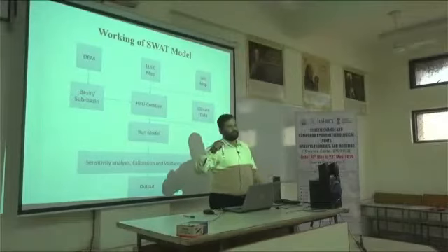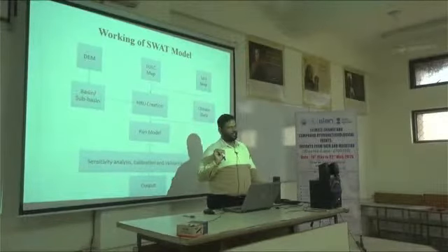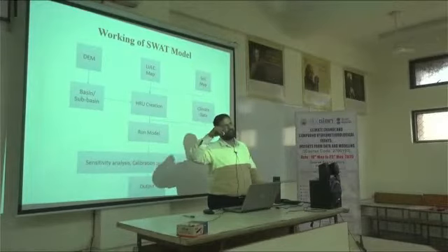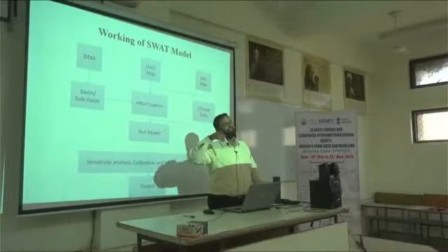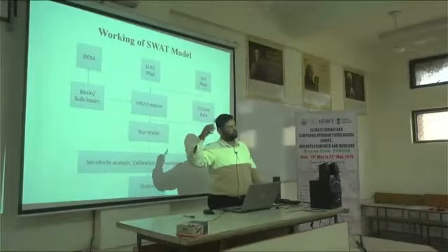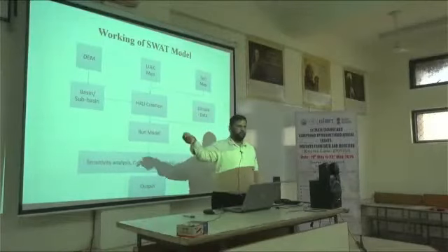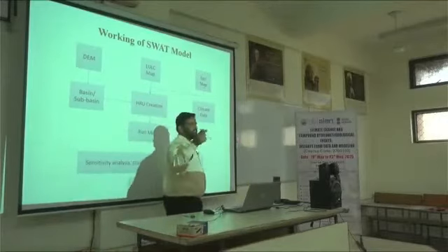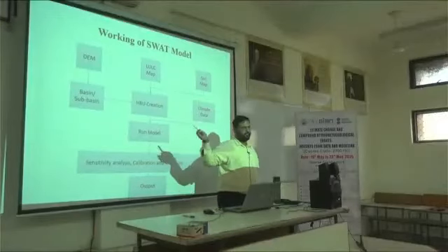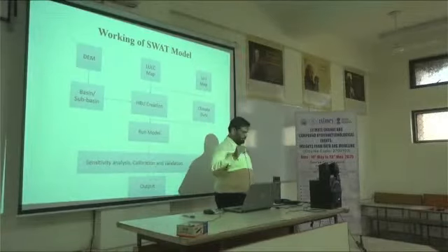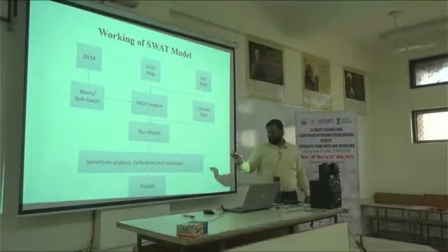You have to prepare your own database. That is the only way. Otherwise, if your catchment area is small, you can go into the field and collect some soil samples. Or there are readily available tools, like soil pedotransfer functions, software of that kind. If you have some samples within your catchment, you can give those samples to that particular software, and it will generate, with the help of interpolation and other techniques, some statistics and soil properties related to your catchment area. So these are the third input.